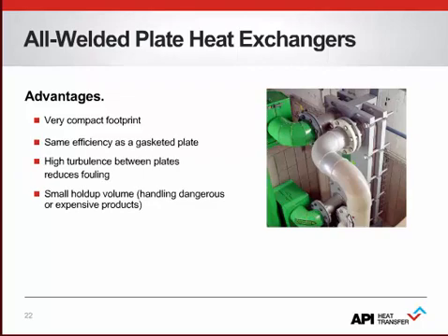The fouling factor that is typically used in plate heat exchangers is only 10% of the one used in shell and tube heat exchangers.